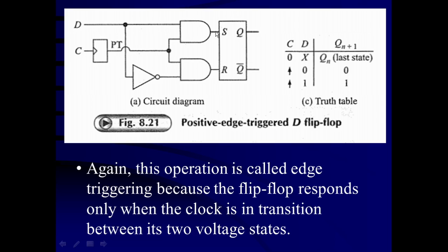That way either a set condition or a reset condition occurs for the basic RS flip-flop, and the flip-flop is set or reset depending upon the value of D.